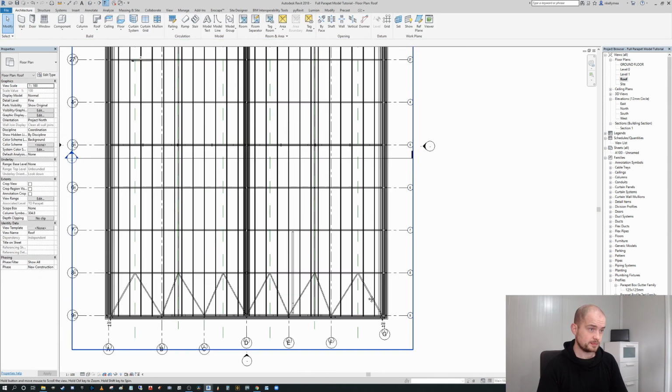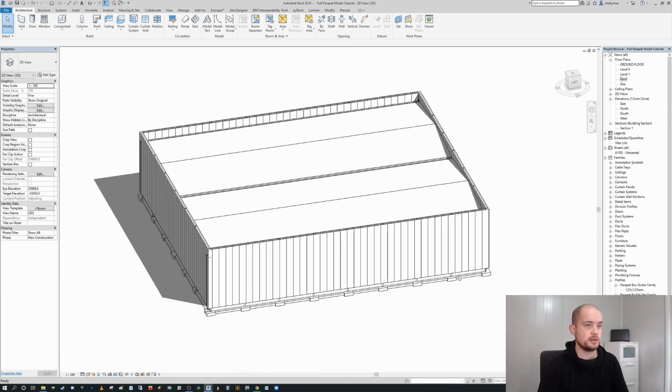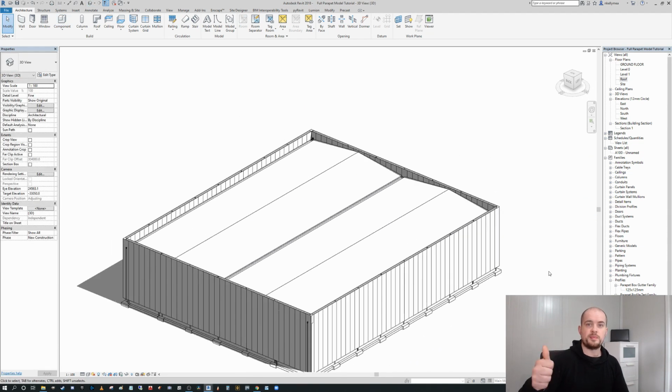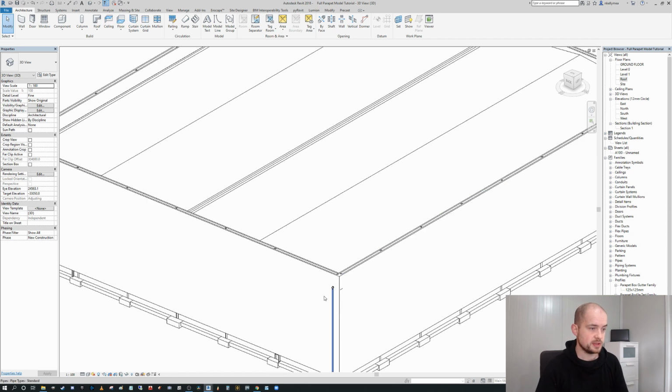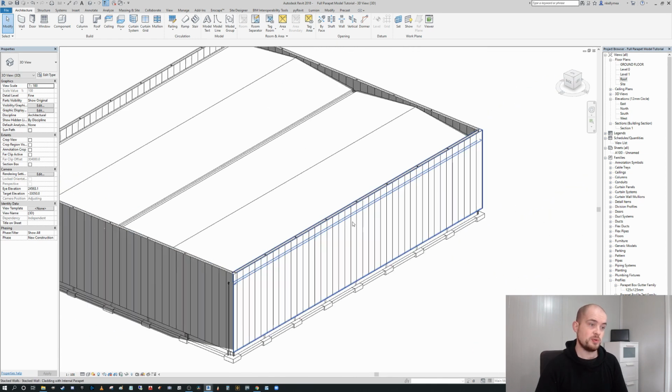Okay. So now we have fully modeled our parapet walls, including the external cladding and internal cladding, our roofs, our gutters, and our downpipe and scupper arrangements on either end. Okay, and again, these scuppers can rotate onto any point in the roof because obviously you'll have some sort of internal crickets on the roof that are very difficult to model.